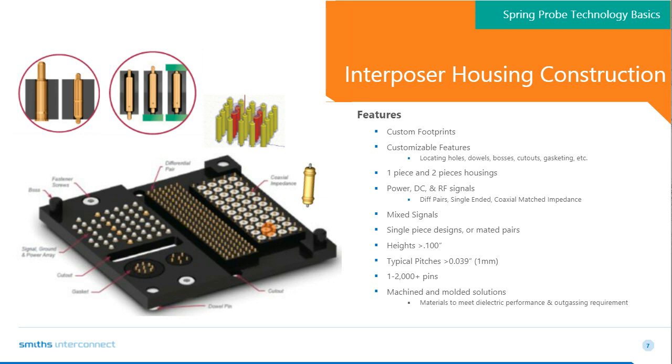You can see we're taking this standalone dielectric single pin with a plastic housing, and then pressing multiple rows of those into another housing. And then you can see that we also have individual pins standing or acting as the grounds that would ground the entire assembly itself. Again, we'll go through a little bit more of that in more detail later.